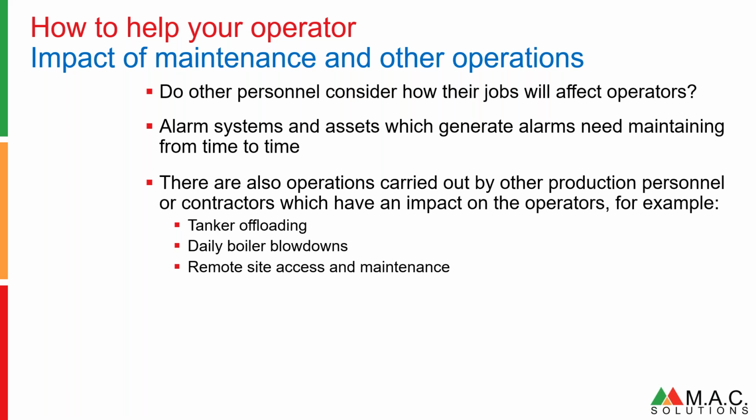If that alarm happens normally, you've got no water in your boiler, potentially there's a potential explosion. They need to get an operator to go to the boiler house, which is going to take 2 or 3 minutes to go in. You're going to take them away from doing important things. So by not telling the operator, you're putting a whole scenario in operation that doesn't need to happen. The operator has to respond. He shouldn't need to.